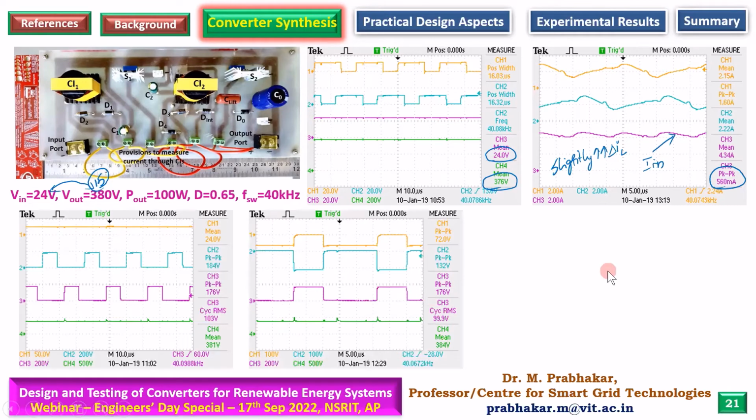Okay. Then we wanted to check the voltage across the switch. This is voltage across switch 1. This is voltage across switch 2. You will see that the peak voltage is slightly on the higher side. I'll again zoom it for additional clarity.